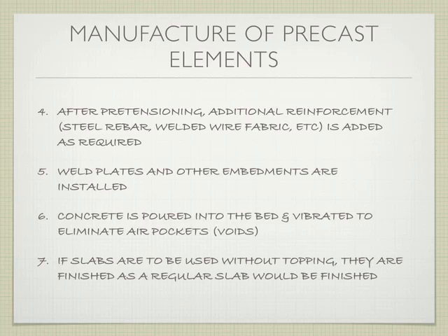So after we stretch those tendons, they'll put in any additional reinforcing, any extra weld plates or anything that needs to be embedded in the concrete, any extra things that are specific for this particular beam. They'll put those into place. Then they'll pour the concrete into the bed and they'll vibrate it to eliminate any of the air that's around it. If slabs are to be used without topping, they're finished right then. Most of the time they're used with topping, so they're left rough on the particular surface.